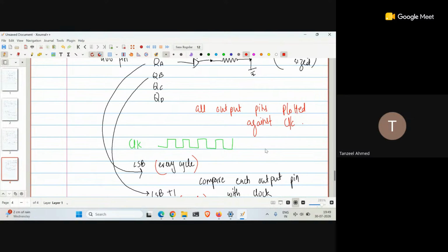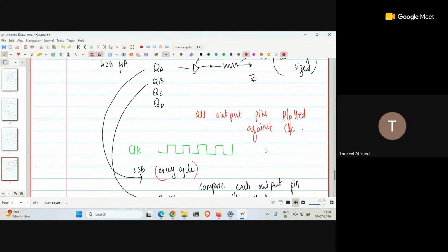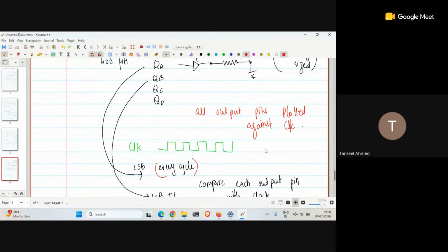How you will get the reverse counting output, I leave to you. It is possible to do. You stage your counting output to go through some inversion and then some combinational logic. Just inverting it entirely may or may not help you out. You need to check that. You need to write up the truth table for that and see whether simply inverting all of these works.